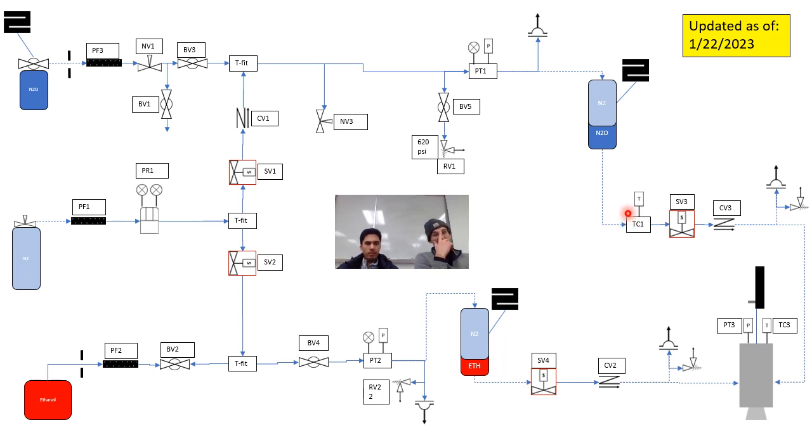And the way we're going to get it to 0 degrees Celsius is to have this run tank, and as much of this surface area of the feed system in this area, we want it to be submerged, whatever safely can be submerged, in an ice bath. The ice bath will cool whatever it is from room temperature down to at a minimum of 0 degrees Celsius.